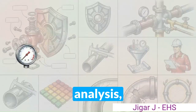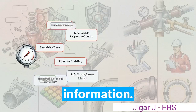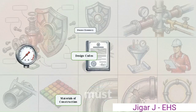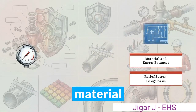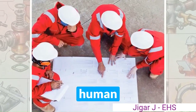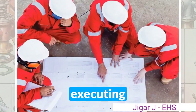Before a hazard analysis, OSHA mandates compiling complete process safety information. This means gathering precise data on toxicity, operating temperatures, and flow rates. These raw metrics must be synthesized into finalized piping and instrumentation diagrams, material balances, and relief system designs. With the documentation complete, the analysis requires a specific human element. OSHA enforces strict composition rules for the team executing the PHA.